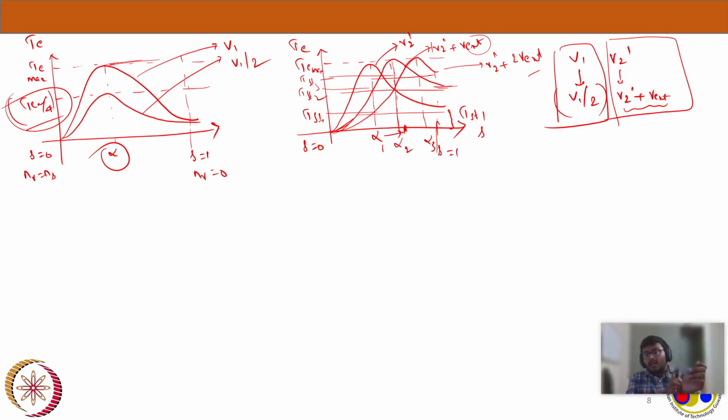Now, you can find some very interesting thing. I will keep on adding external resistance to my rotor circuit until I get maximum torque as my starting. So I have added till that point. So see, this is my starting torque. So TEM itself is my starting torque.